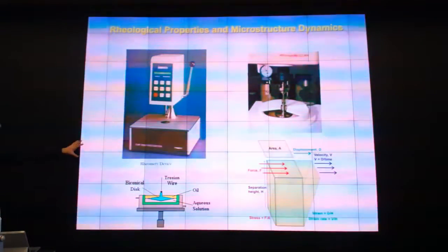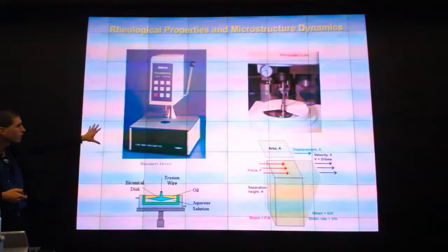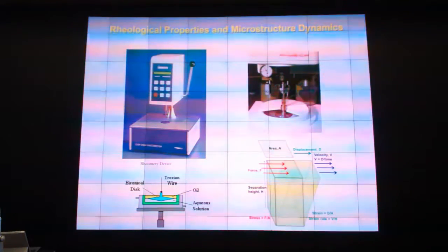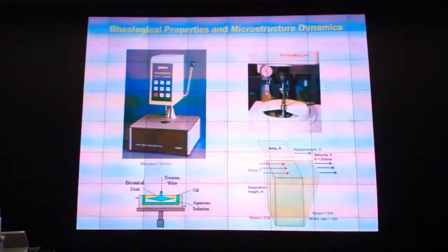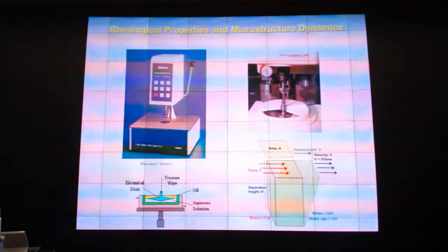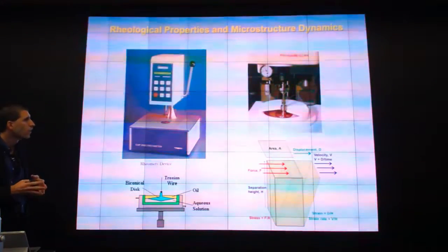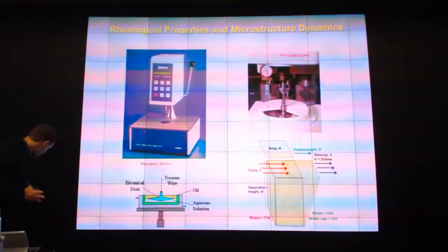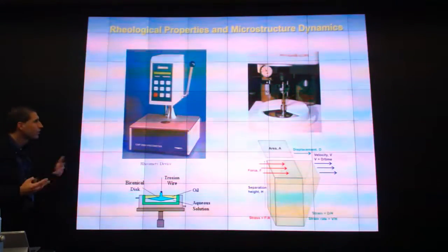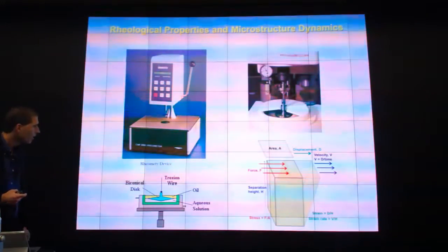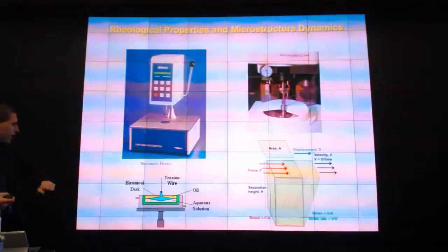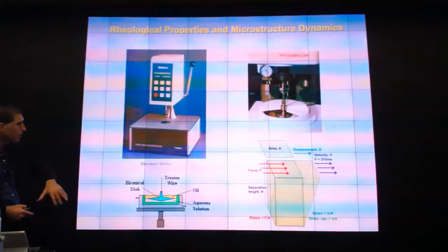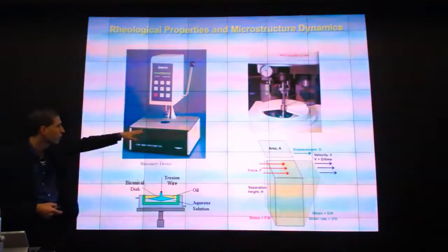Okay, now what I didn't say much about this morning, but is in the current codes, which would be of interest to you, is that oftentimes one way these materials are characterized is to look at their rheological properties. In particular, looking at something like a rheometer, you would apply a torque and look at the corresponding angular velocity of your probe, or the other way around.